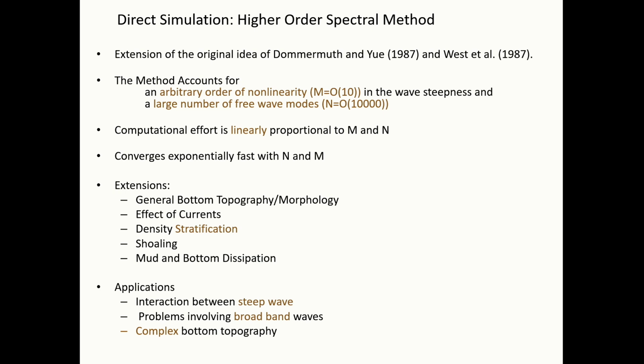All right. For direct numerical simulations, there are two methods. I'm just going to talk about one. It's called the higher order spectral method. So it's not a brute force finite volume, it's a spectral method. It's very efficient for simulating a 10 kilometer by 10 kilometer area relatively easily on a laptop. Of course, it has the capability of using parallel computing, so we can take a higher order of nonlinearity into account. We cannot simulate wave breaking, which is extremely nonlinear, but we can simulate pretty steep waves.